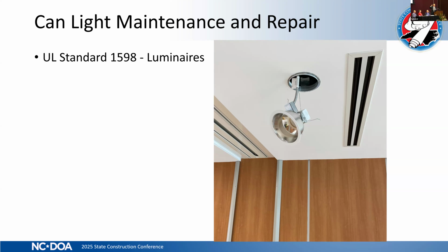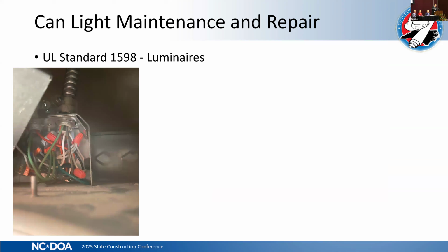So our electrical shop, which may be sitting in this room, called me over, stared me down and said, "What did you do? You let them put a fixture in here that I can't change the driver on." And I looked at it carefully and thought, well, I'm not quite sure. So I went up above the ceiling, and there you can see the picture I took. 5 inches away from that 6-inch aperture, there is a box.